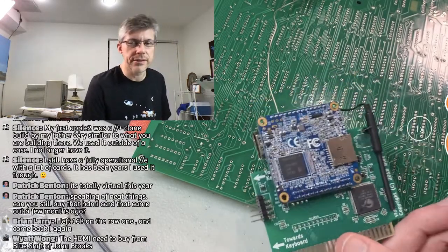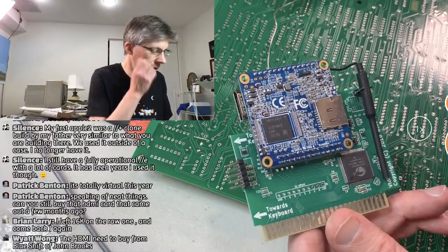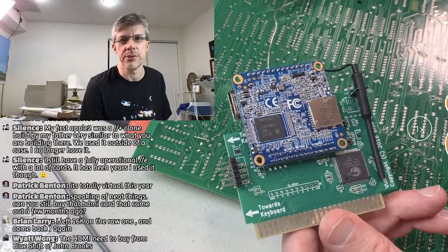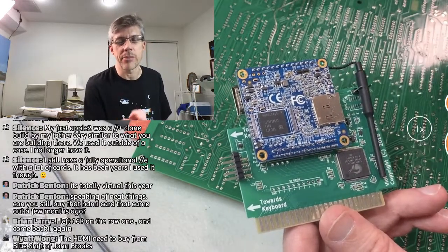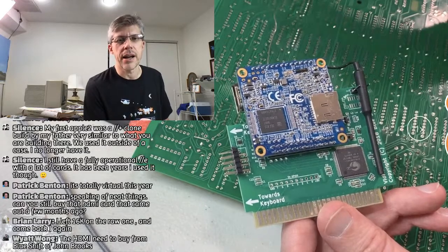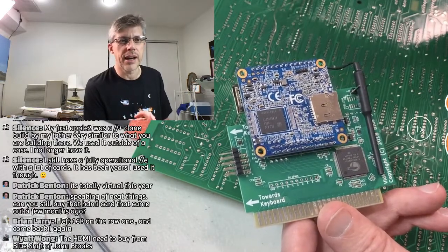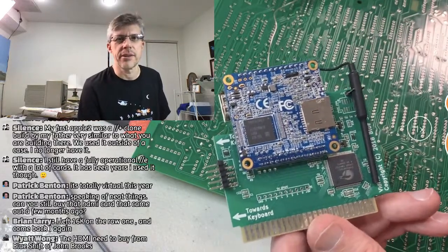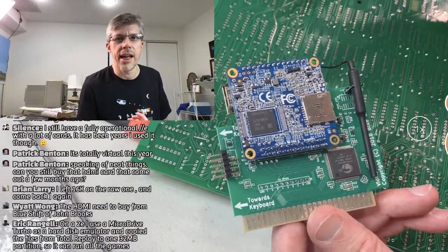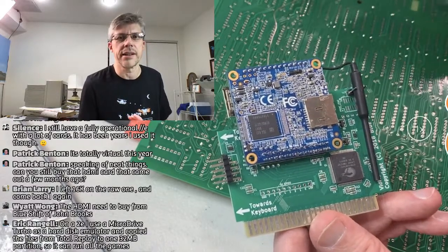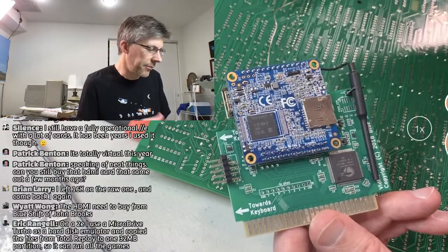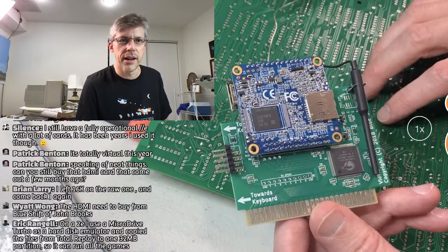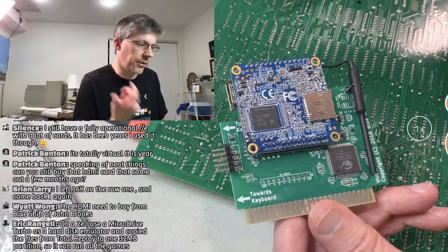And this card, it's really interesting the way it works. It's not taking the actual video signal from the Apple II and converting it. It's actually looking at the memory itself inside the Apple II, and every time, 30 times a second or 60 times a second, whatever, it's reading the memory, processing it on board, and then converting that to HDMI. So it's kind of straight from the Apple II memory directly to HDMI.